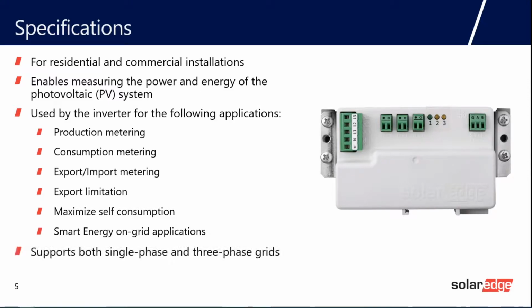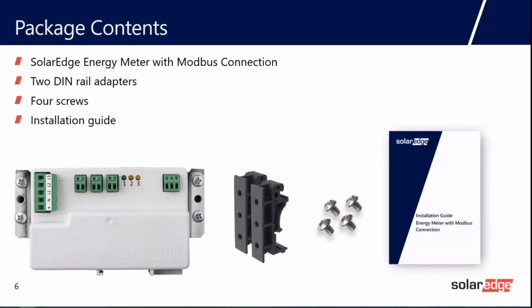The meter supports both single-phase and three-phase grids, and requires the installation of current transformers. These CTs are also available from SolarEdge. Included in the meter packaging are the SolarEdge energy meter with Modbus connection, 2 DIN rail adapters, 4 screws, an installation guide.